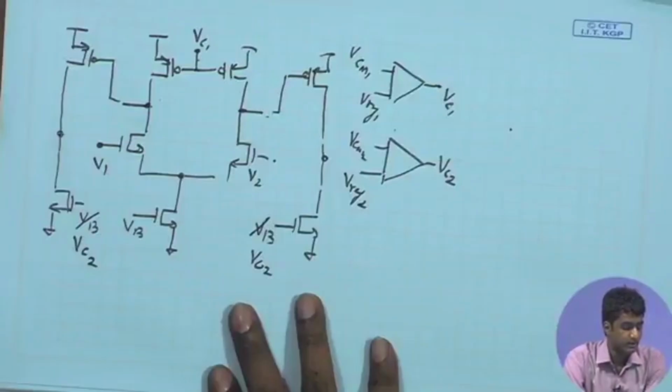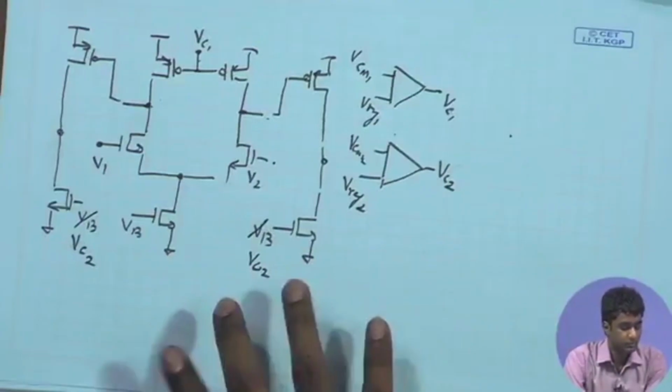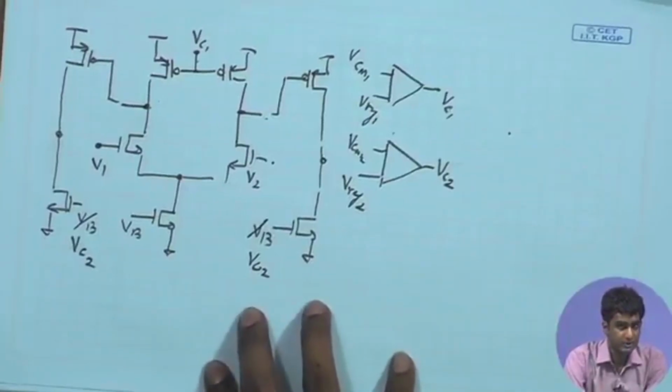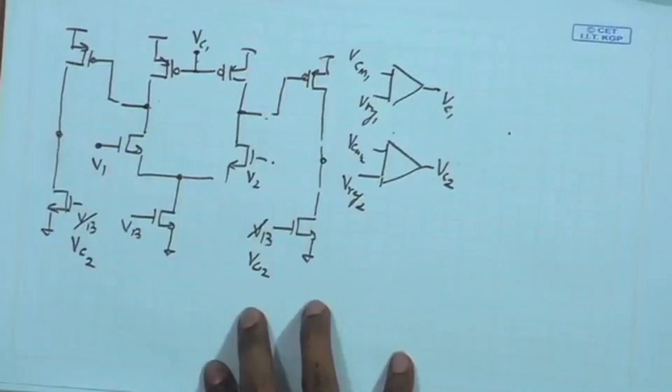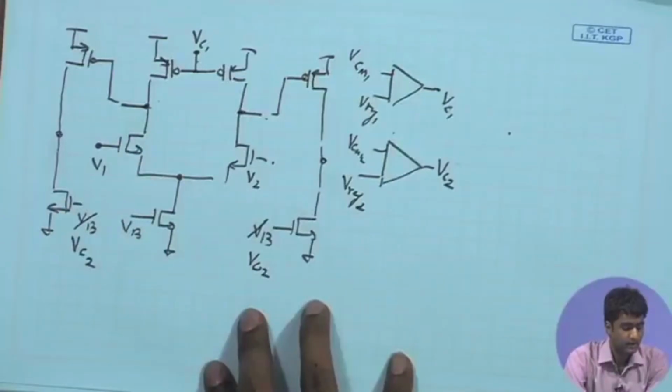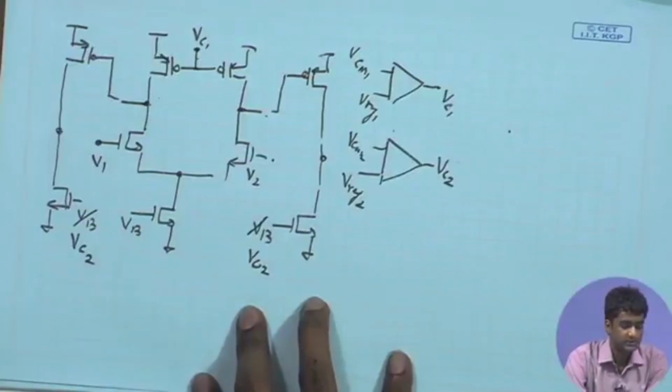Therefore, once again the stability analysis of the feedback becomes important, and for stability analysis we can first of all find out the feedback topology of this circuit, look at the overall high frequency poles coming in this circuit, and then look at the considerations that we can make to ensure overall stability of the feedback loop. What kind of compensation, what kind of components are supposed to be added, so that we can make sure that the overall loop is stable.